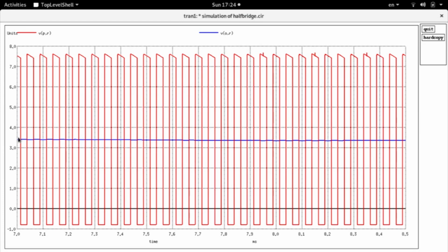So you can calculate what the expected output voltage is. Of course, you should remember that what appears across the primary of the half bridge transformer is VDC by 2, and that gets multiplied by the turns ratio and then by 2 times the duty cycle of the switches. The duty cycle we have set at around 25%, so 2 times the duty cycle is 50%, with VDC by 2 coming into the picture, and therefore you will see the output accordingly here.